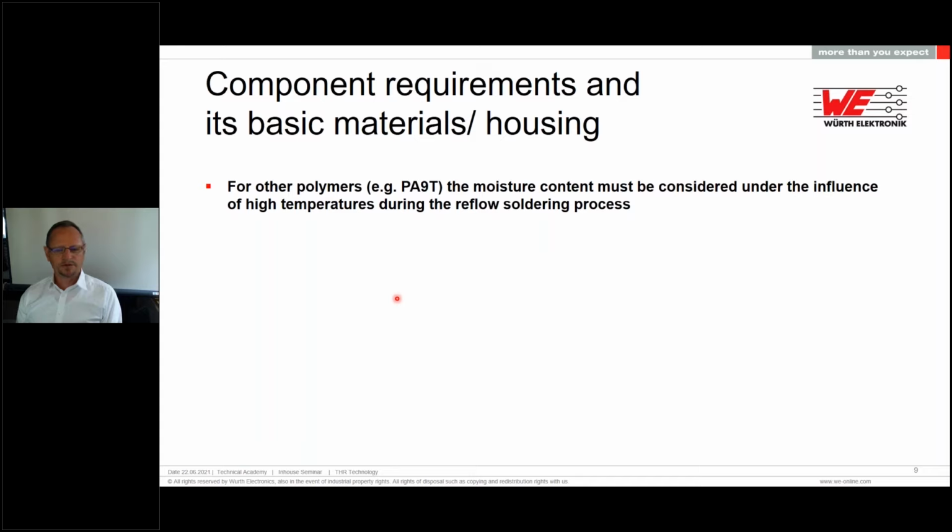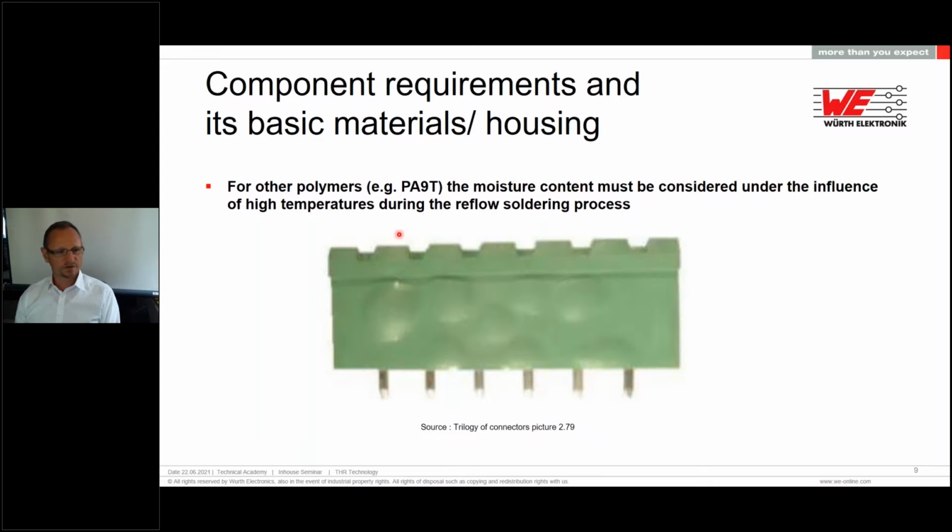What's going to happen for some polymers, like you see the PA9T, which is very common, there is moisture inside, and it tends to absorb also moisture from the environment. And yeah, what happens in the soldering process looks like this. So if the moisture inside expands explosively, because it's getting hot very quickly, then you see the bubbles here, and this one is called the popcorn effect. Maybe you heard about that.